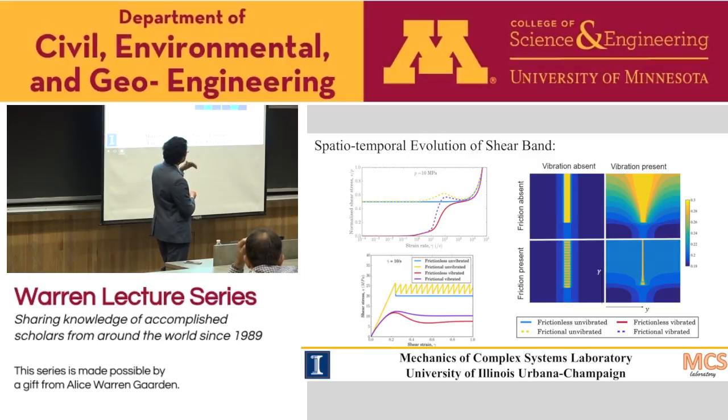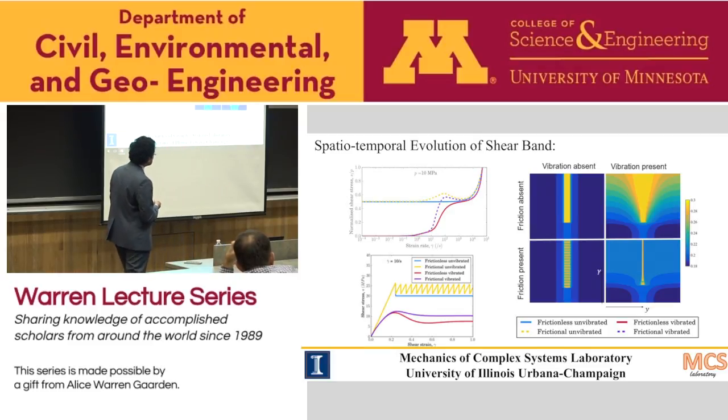Now, if you have vibration, then vibration tends to fluidize the system and will tend to delocalize the shear band. So eventually it can localize, but because vibration induces plastic deformation everywhere, it would eventually be delocalized. Although here in a frictional system with vibration this appears to be more localized, actually the background compactivity here is comparable to this magnitude.